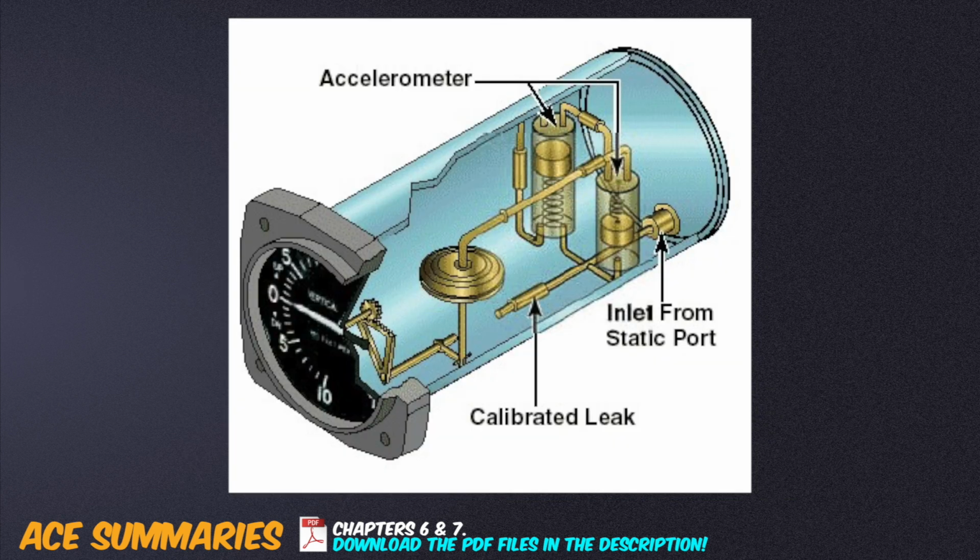An IVSI uses two spring-loaded weights between the instrument and the pointer, which use inertia to display a rough vertical speed change immediately following a change of altitude. This removes the lag error of a typical vertical speed indicator, which works by metering the instant rate of change of static pressure inside a capsule in comparison to the static pressure in the instrument case. The instrument case has a metered release valve and thus cannot react instantly.